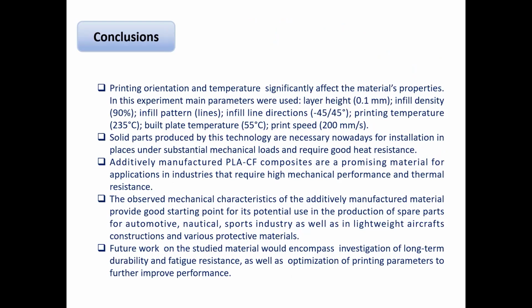As a conclusion, we didn't mention in the beginning, but we talked about layer height, infill density, and infill pattern. We use lines as the infill pattern. We use line direction minus 45 degrees. It is obviously the best orientation.